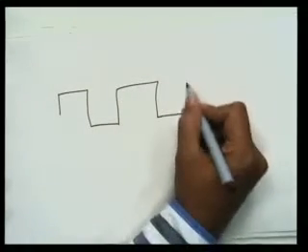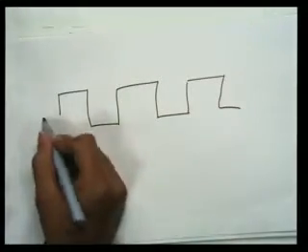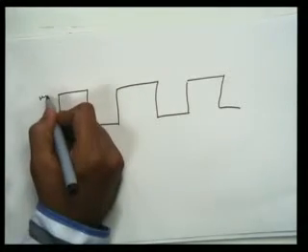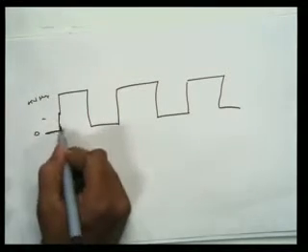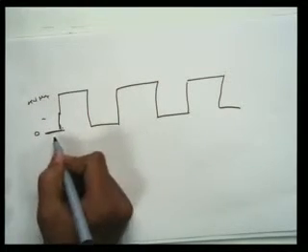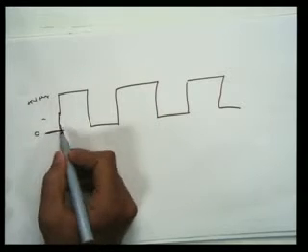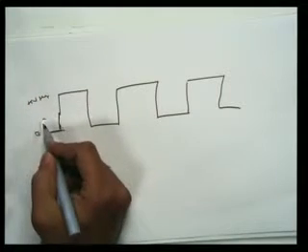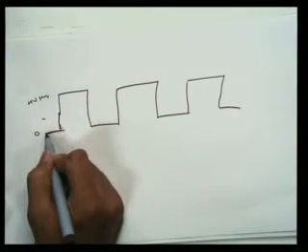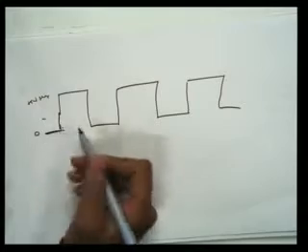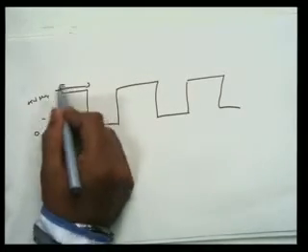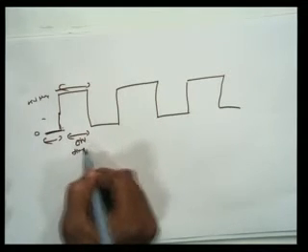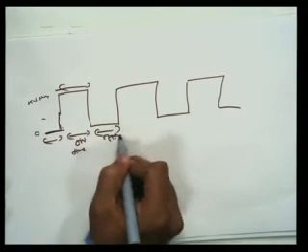What is this pulse? Basically it is a digital signal, which will have 0 and 1. This is the 0 level and this is the high level. High level is the plus 5 volts level. I am applying this pulse voltage as an input voltage. It will automatically toggle between 0 and high, and high means 5 volts. For a certain time it will be 0, it will be off, then for a certain time it will be on. So you can see this is the on time and this is the off time.